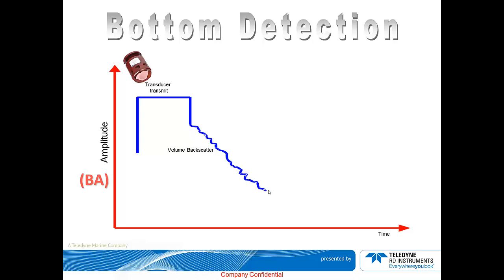But what is this BA parameter? The BA basically sets the bar for an acceptable return signal's echo intensity expressed in the unit of counts. Anything above it is considered good and accepted, and anything below it is considered bad and rejected.